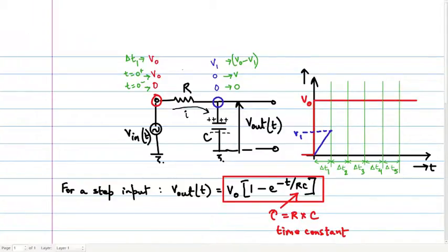If you notice, the potential difference across the resistor is now reduced from what it was earlier. Therefore, the current that it lets through also is reduced. Charges still get deposited on the capacitor, but now because of the lesser current, they get deposited at a lower rate, which means that the capacitor voltage still rises, but at a rate more gradual than what we had in delta T1.